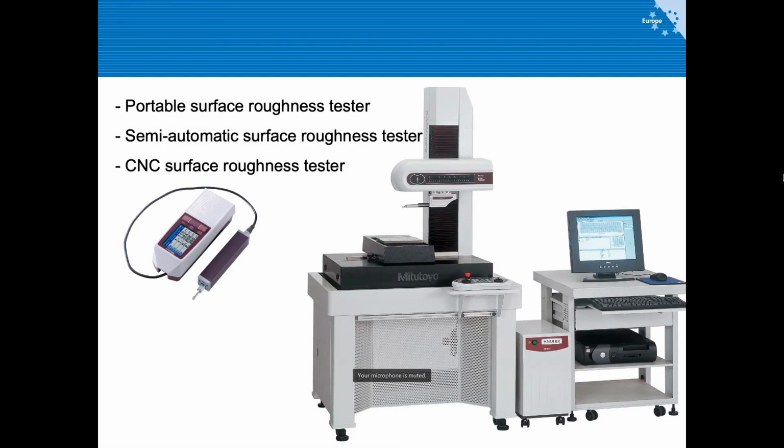And if you want to do it with non-contact measurement tools, yet again, there are two ways you can measure. As mentioned in this video I showed you, you can measure with the contact type of profilometers, like shown here, when you physically slide across the surface with a very tiny needle, or you can use some non-contact methods like confocal microscopy, laser interferometry, etc.